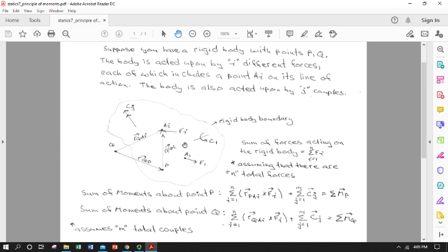An axis line with a little rotational arrow around it is another way of showing moment or a couple. So pure moment, no force. So we've got this symbol, and this symbol means the same thing. So you have couple 1, maybe 2, 3, 4, and ending up at J. And we have many forces.